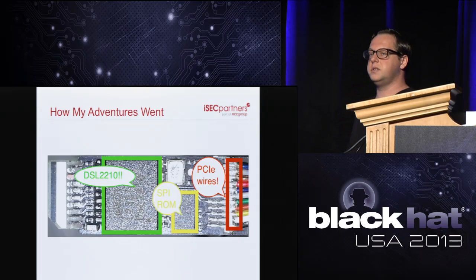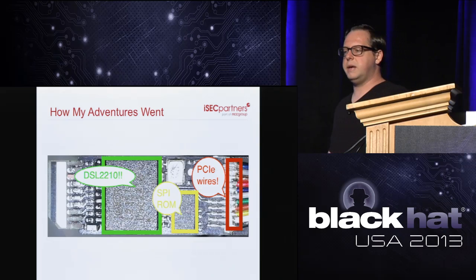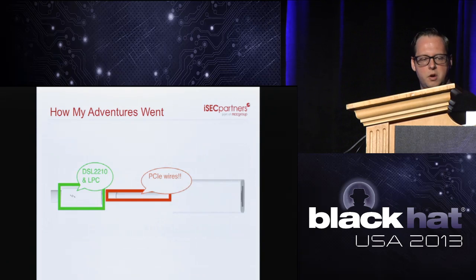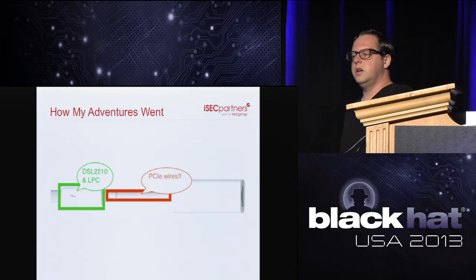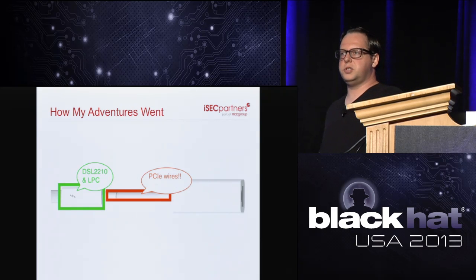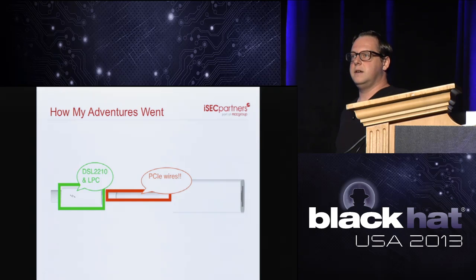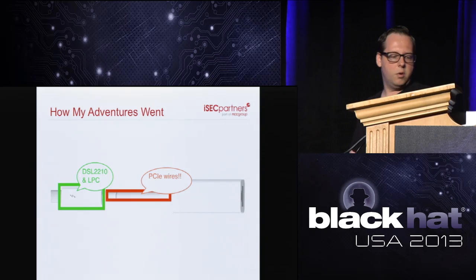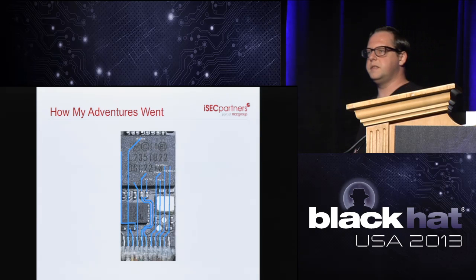and we can start looking at what things do what. So checking on the SPI stuff, we know that that little device over there is an SPI ROM, because it's connected to the SPI lines of our Thunderbolt controller we've mapped out. We've also mapped out that the wires coming out of the device are PCI Express lines. So coming out of the connector down this wire, it's just straight PCI Express. And we know from our reverse engineering what pins are doing what. So we can start making a map on this device as well.